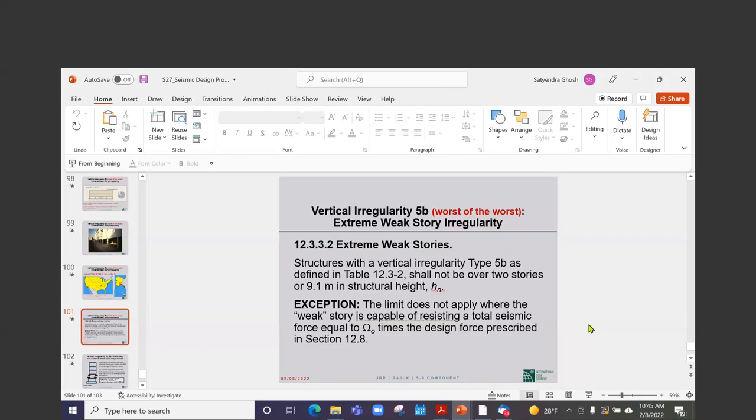I kept on saying, I don't know how many times, that gravity loads do not cause lateral drift, any appreciable lateral drift, unless you have a very significant lack of symmetry. So for the vast majority of buildings, it simply does not matter how much gravity load you have sitting on your structure when you calculate your drift.